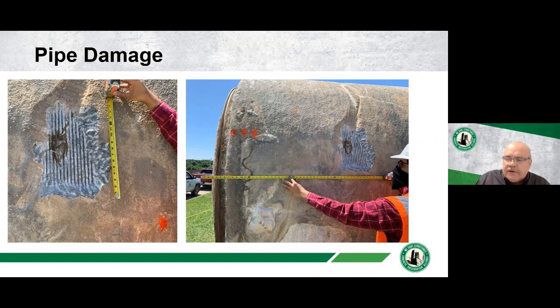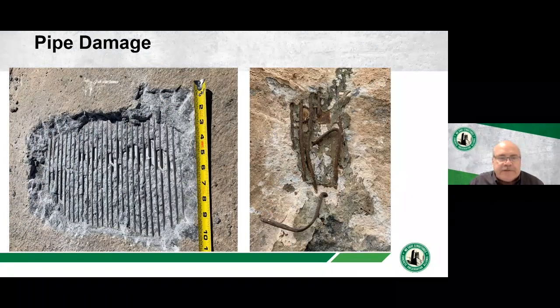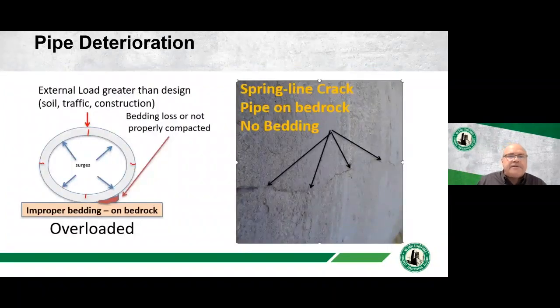We've had the fortunate opportunity to test pipe sections in service as well as pipe sections forensically after there have been some failed pipes. And there's an outer coating. I've got a diagram of what PCCP is, but this is the damage that we're trying to identify early on by testing the pipe from the inside or from the outside and catch it before it breaks.